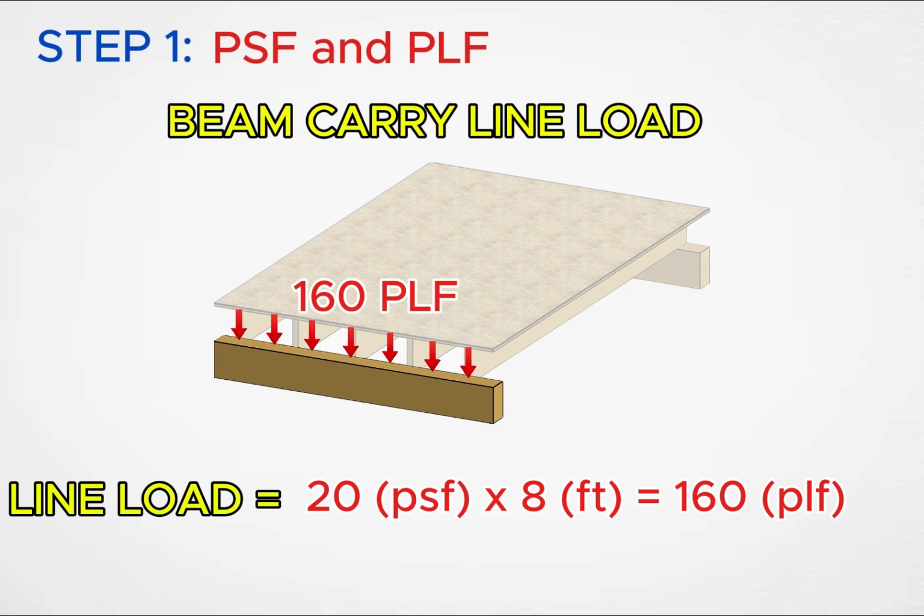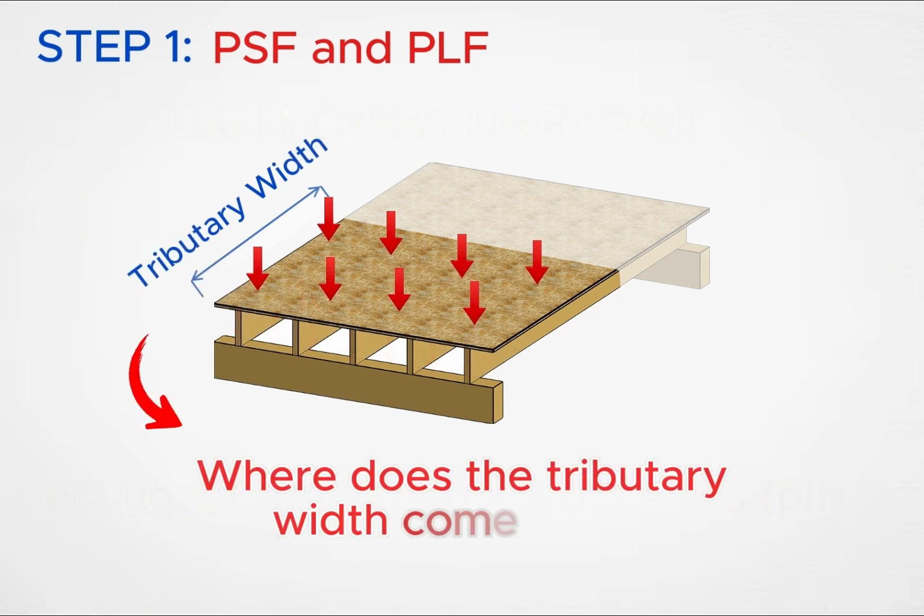Today we learned how to convert PSF into PLF, but we're still missing something important. Where did that 8-foot tributary width come from? How do engineers determine that value? That concept is called tributary width, and it's one of the most important ideas in structural design.